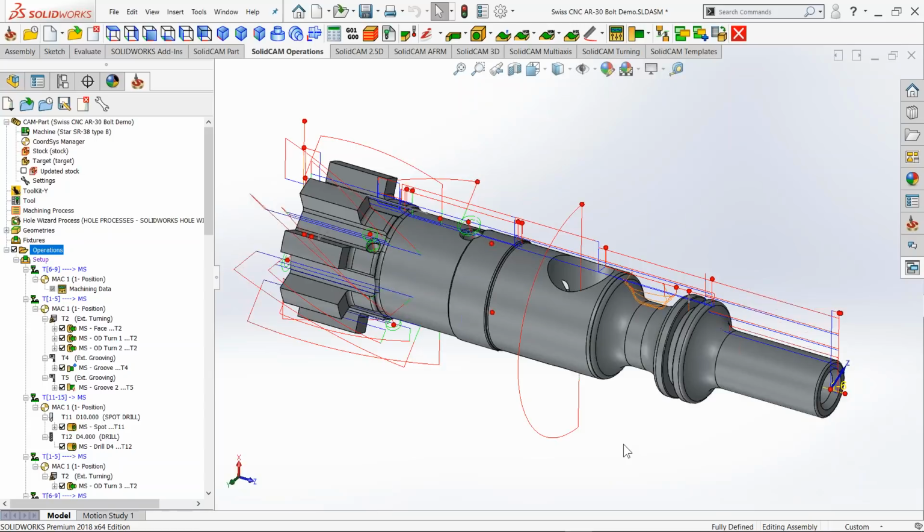Yes, we do. Basically, whenever you have part transfer, what I showed you over here, when you grab the part with a back spindle, everything is basically in superimposition mode. It means that you can do turning, milling, everything, where you will see the part being moved along the Z1 axis, and the back spindle follows that position. It's a pity that I didn't prepare that one, but definitely yes. Superimposition is just part of the Swiss type module.